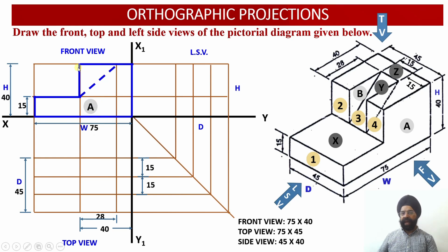So surface A I have marked independently. This total solid surface is going to be my surface A, and within this surface A there will be a dotted line which will correspond to the internal vertical edges corresponding to the webs over there. So this surface will be my surface B. Okay, so this surface B is contained by surface A. Whatever portion of surface A I have darkened is completely going to represent the total view from the front side of this particular solid.